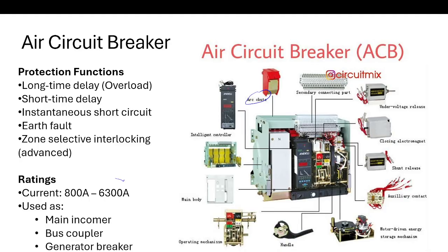Zone selective means if there are multiple circuit breakers, they are programmed in such a way that the breaker nearest the fault breaks first.